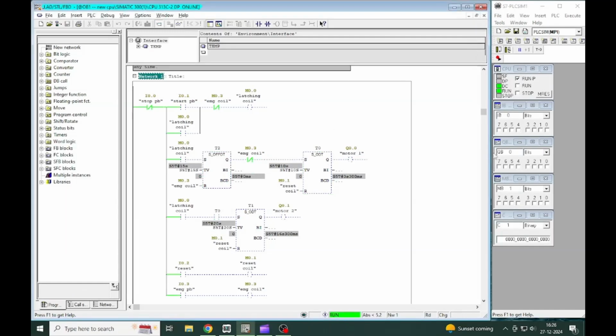I found an error in this logic. When someone presses the stop push button before the motor starts to run, the off delay timer can still turn on the motor. I mean, when anyone starts the system by mistake, or turns off the system immediately by pressing the stop push button. This error is also overcome by pressing the emergency push button. But the motor actually does not turn on, due to the time delay. So, why am I pressing the emergency button? I pressed the stop push button. And after 15 seconds Motor 1 runs automatically for a few seconds, which is dangerous.